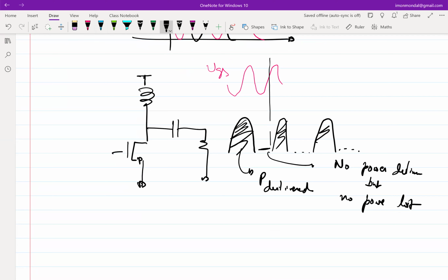Right. So essentially, the transistor should be switched on during one half cycle and switched off during the other half cycle. So all I have to do is to ensure that this bias, whatever I have, is equal to VTH. And on top of that, if I apply input, then the effective V overdrive goes from 0 to maximum and then again 0. The negative half cycle doesn't come in. So which means here, if transistor is off, no power delivered; transistor is on, high power delivered. So this in principle should give me good efficiency.